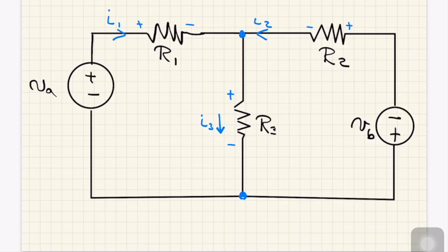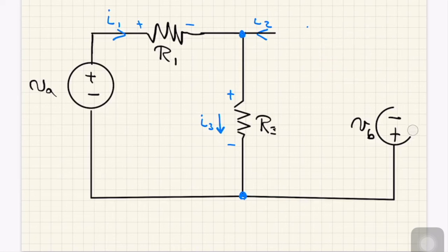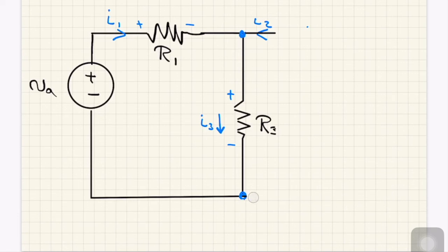And obviously, getting rid of the branch that includes I3, which was our solution, is maybe not such a smart idea. But we could get rid of this whole branch on the right-hand side if we set the value for R2 to be very large. Because if that becomes large, as in toward infinite, then that whole branch goes away. So now I can literally erase that entire branch and simplify my circuit quite dramatically. I can get back to a really simple little circuit here in which there is no I2 current.